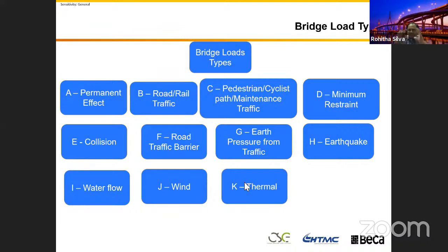The way we design the bridge, we design the bridge for traffic flow. Please remember that. We design the bridge to support the traffic, then we check for all other conditions. For example, collision, earthquake, the water, the flood loading, the wind loading, all those things we check. We check and we take the necessary action. Please note that, don't mix it up.